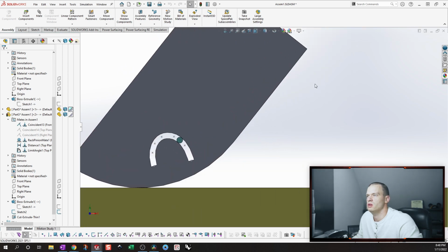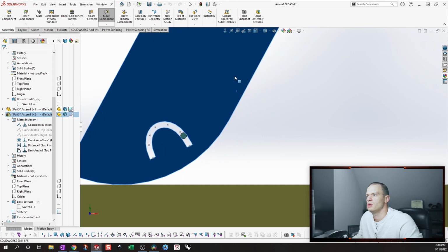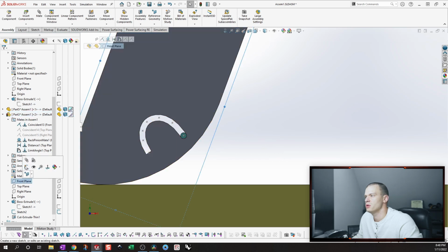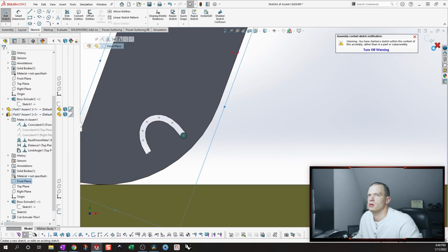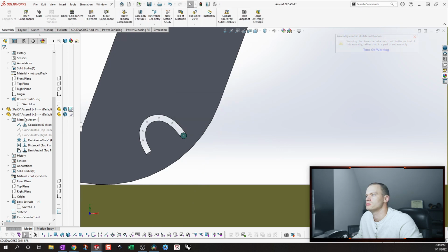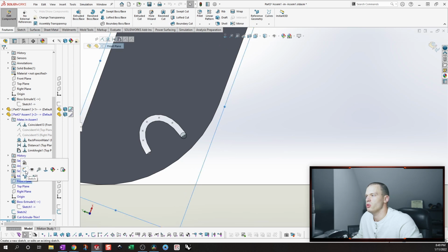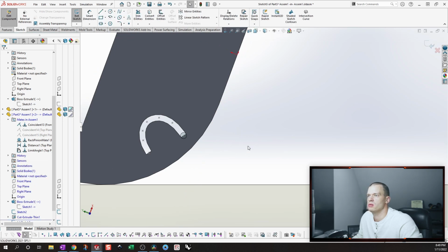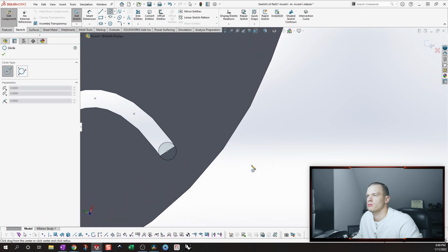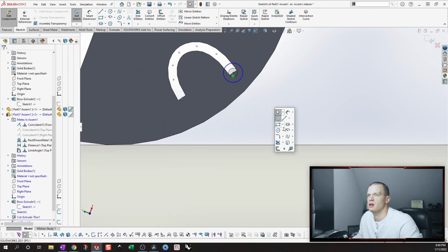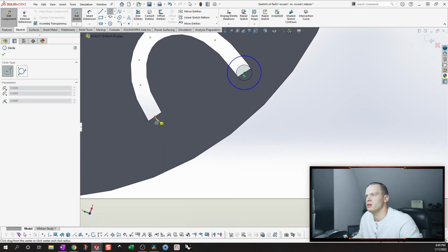And again, you'd add tolerance in there, and you'll have to cut circles at the end. But again, that's pretty easy, right? We just go in and use our endpoints that we already described. Now we want to make sure that we're getting the correct endpoints off the sketch and not assigning it to that pin, or they'll end up floating around.